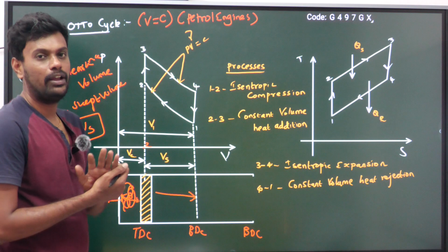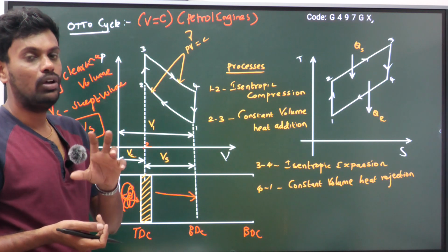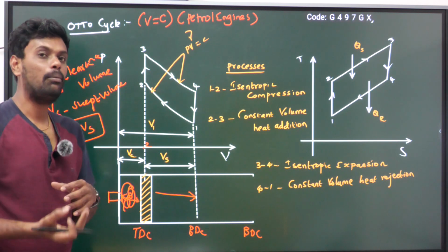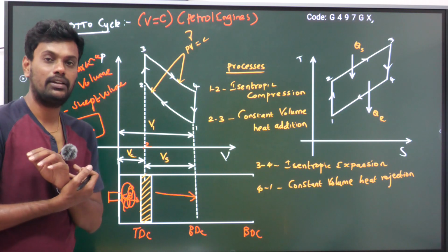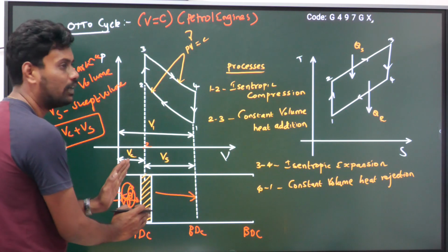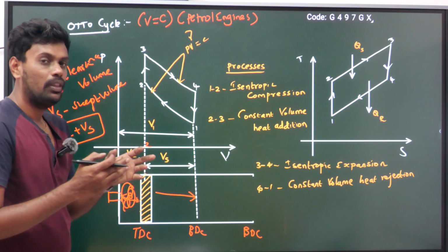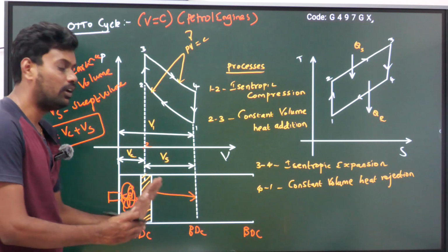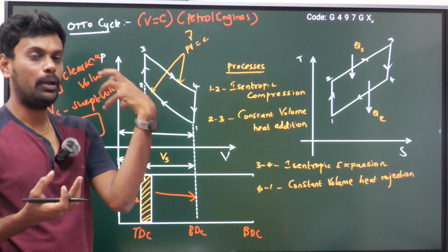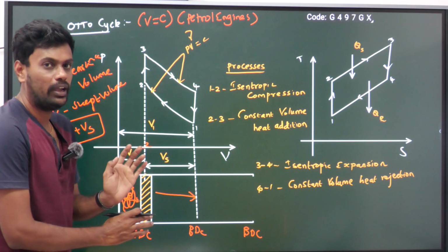Now you see what is happening, how the Otto cycle, how the petrol engine is working. During the suction stroke, there is a supply of air, and the air and petrol mix in a petrol engine and enter the top portion of the engine cylinder. The piston will be initially at top dead center. The air-fuel mixture coming inside pushes the piston from TDC to BDC. When it is moving from TDC to BDC, there will be some vacuum inside the engine cylinder. Due to that vacuum, the air and fuel mixture comes inside the cylinder and occupies this whole space.